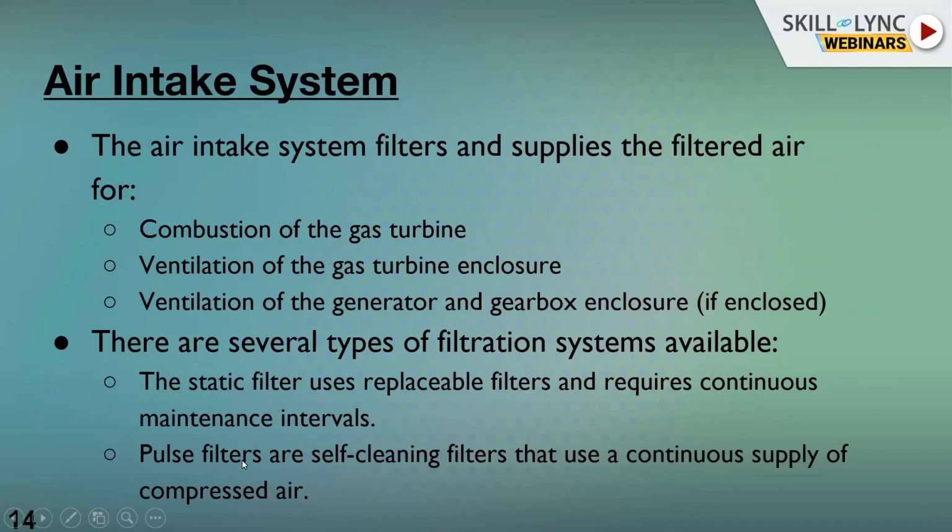Okay, and the other type of filter we have is called a pulse filter. Pulse filters are basically self-cleaning filters. How do they self-clean? They are supplied with compressed air. Compressed air is blown onto these filters so that the buildup will be removed periodically as designed.